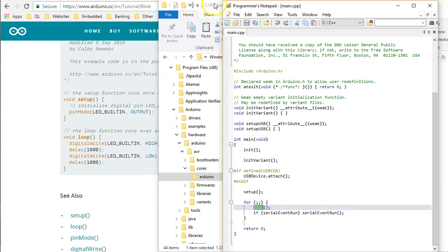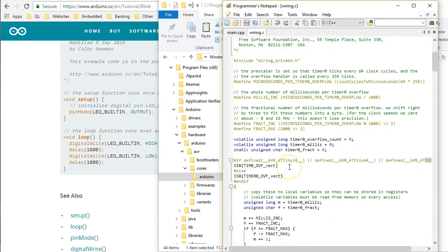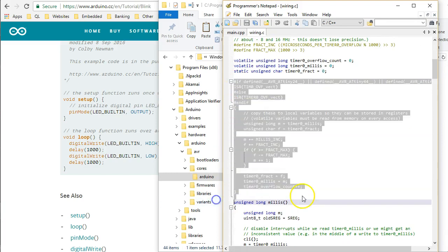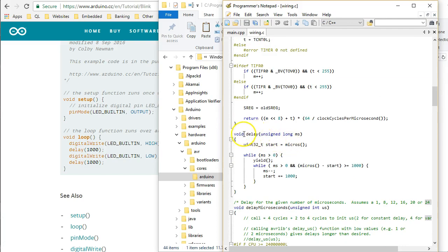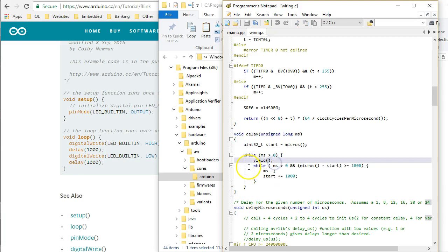Arduino has, of course, also the foreground level consisting of interrupt handlers. Here, for example, is the System Clock Tick Interrupt Service Routine, ISR, which increments some counters, just like your SysTick handler. There is also, of course, the matching polling delay, which is perhaps the most frequently used function in Arduino programs.